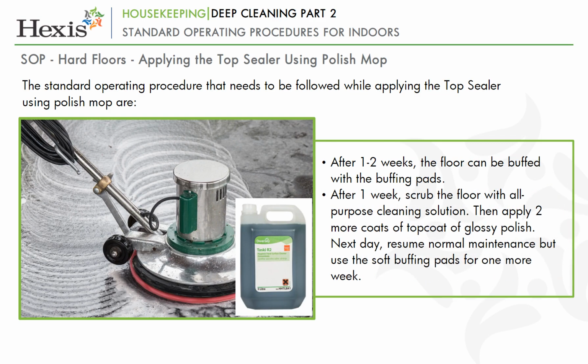After 1 week, scrub the floor with all-purpose cleaning solution. Then apply 2 more coats of top coat of glossy polish. Next day, resume normal maintenance but use the soft buffing pads for 1 more week.